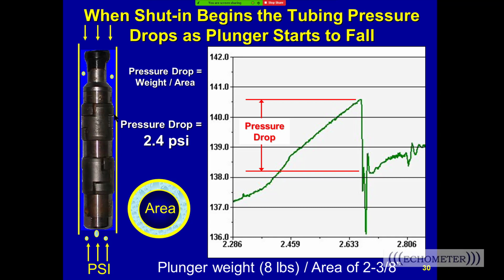And then also, if you have a compact gas gun, manually lock the valve so it doesn't open. So yeah, close the valve before you track the plunger. You'll have a cleanup job after you get done tracking the plunger.